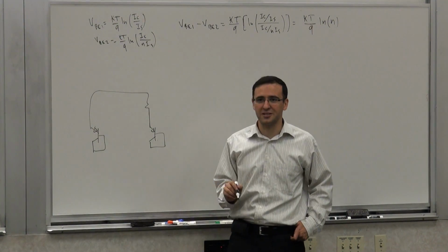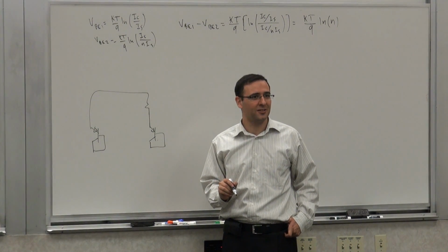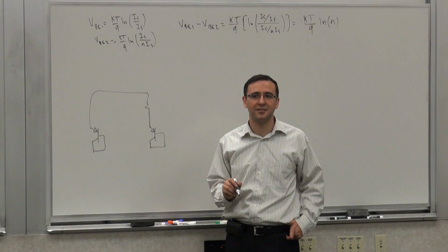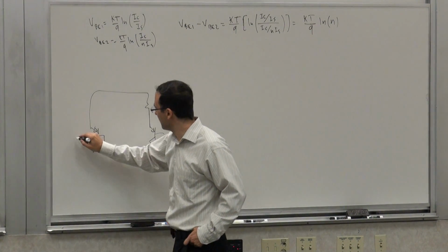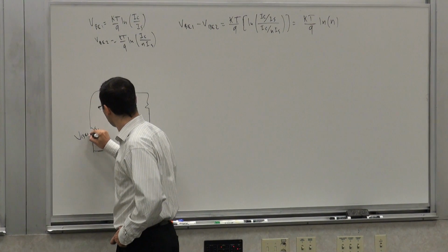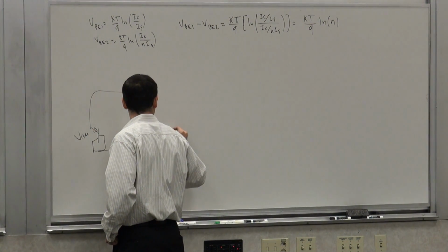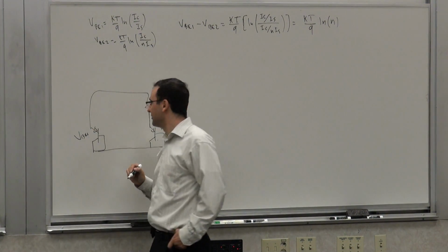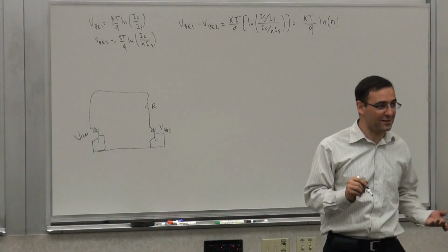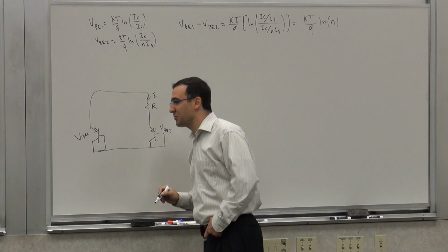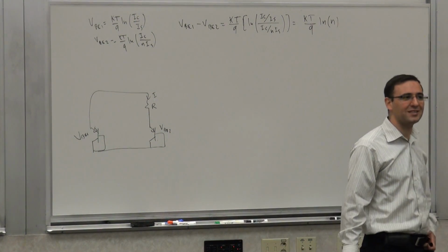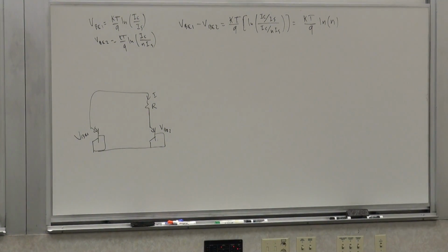The current from this resistor should be the difference of the VBEs, right? Yes or no? This is VBE 1. This is VBE 2. This is R. Do you agree that the current through R is the difference between VBE 1 and VBE 2? What I said is correct, but unfortunately it's 0.